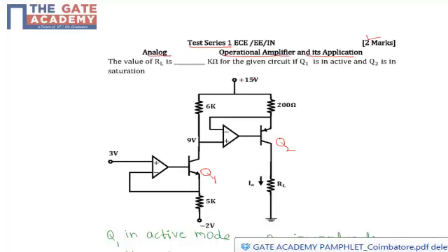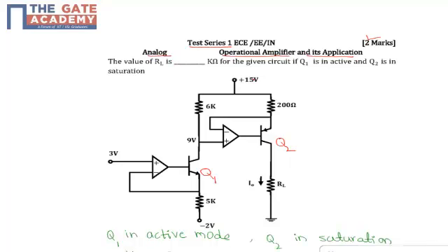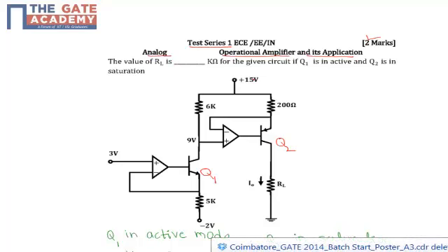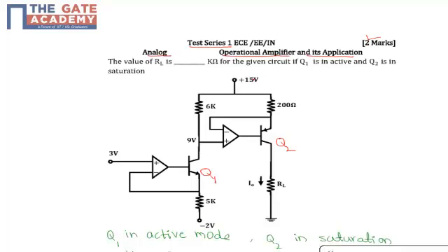First we learn what saturation is. When a transistor is in a fully off state like an open switch, it is said to be cut off. Conversely, when it is fully conductive between emitter and collector, passing as much current through the collector as the collector power supply and load will allow, it is said to be saturated.